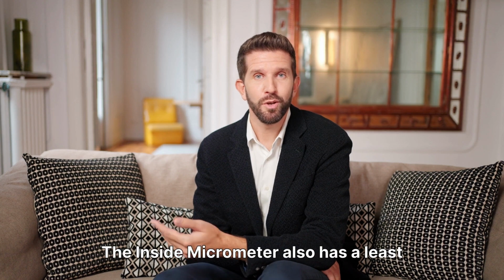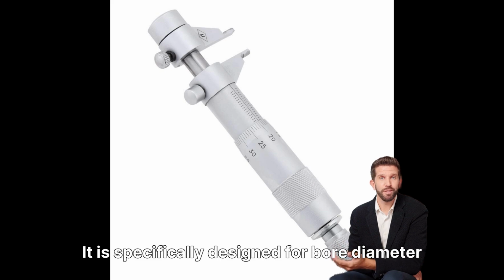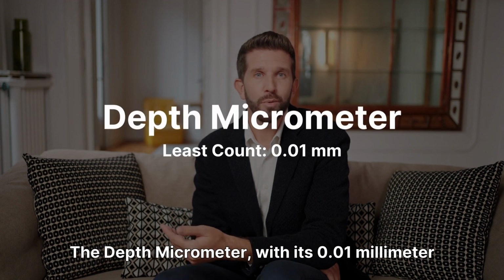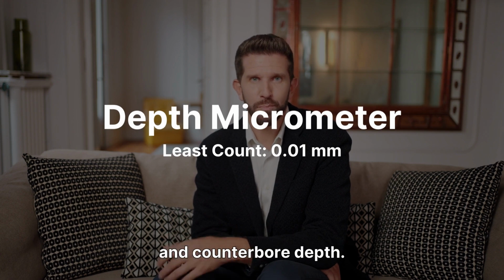The inside micrometer also has a least count of 0.01 millimeter. It is specifically designed for bore diameter and internal precision measurements. The depth micrometer, with its 0.01 millimeter least count, is used for keyway depth and counterbore depth.